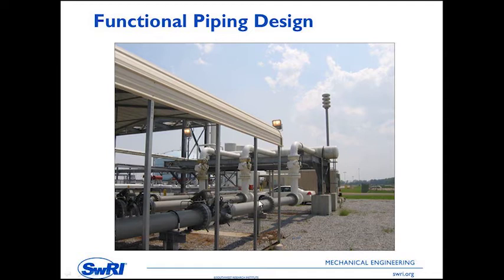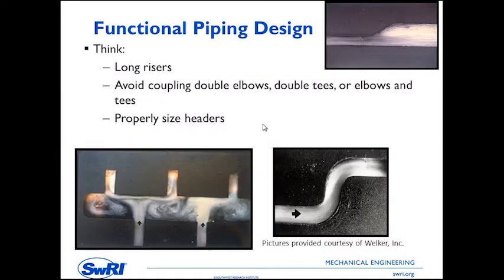The interesting thing about this installation is the diagnostic characteristics for these meters were absolutely perfect as compared to the flow calibration condition. And the reason is we have nice long runs of pipe to recover velocity profile. We have a bend, but we have another nice long run before we come into the T. And minimal flow distortion coming into the entry of the meter tube.